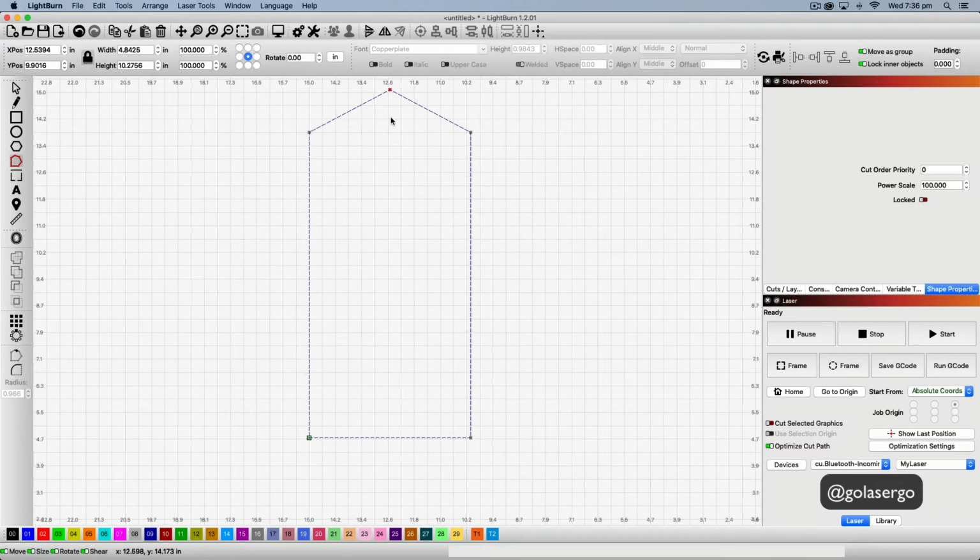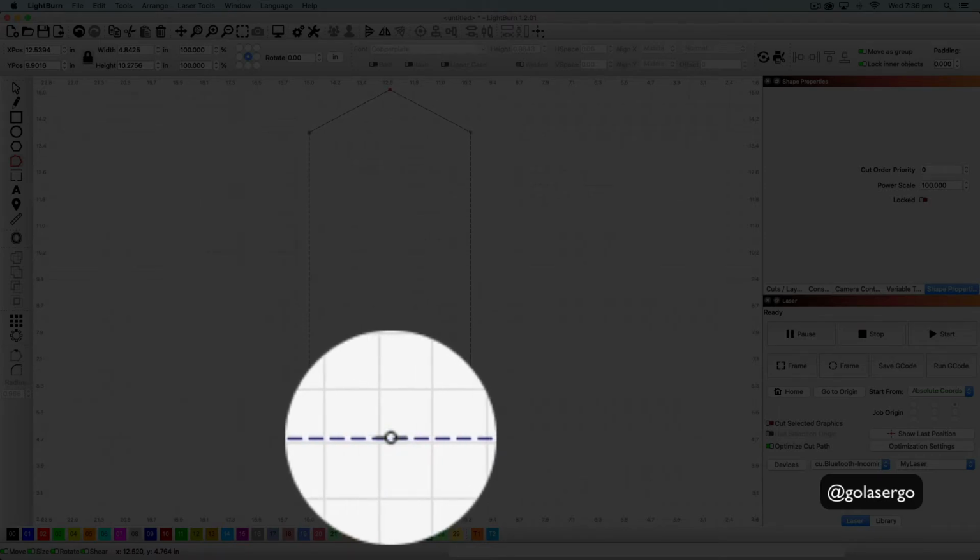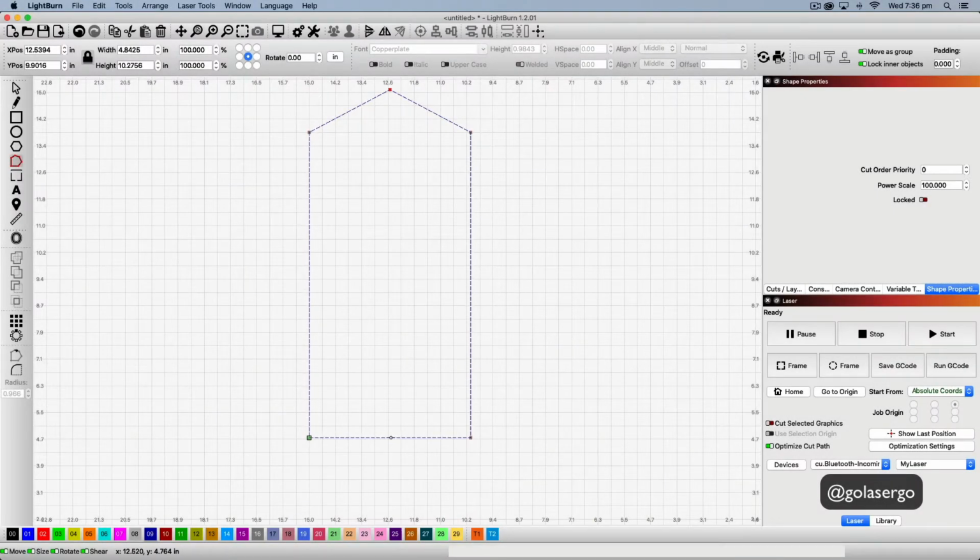And you can add now your little tag hole here and convert that to a tag. Also, you can make a variation on this by coming down to the bottom here. So again, we run our mouse along until we see that circle appear. And while it's down there, I'm going to press the I key on my keyboard. So I've got another node. And then again, I'm going to click and drag this up, holding the shift key again, just to get it.